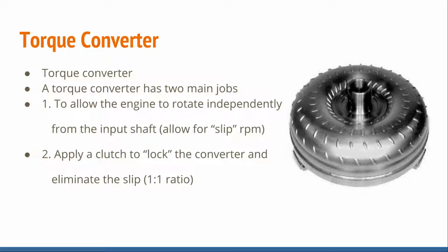Next time you're driving your vehicle, I want you to really pay attention. Say you have a standard 4-speed automatic transmission. Feel the shifts. You're going to feel 1, 2, 3, 4, and then really pay attention, because it's almost going to feel like a 5th shift takes place. What that is, is the torque converter clutch locking up. Now a couple things about that. The transmission has to be up to temp before this happens, and there typically can't be any codes in the system.